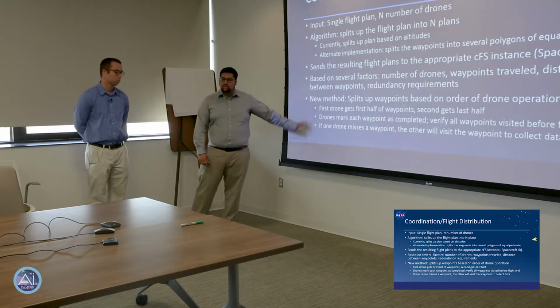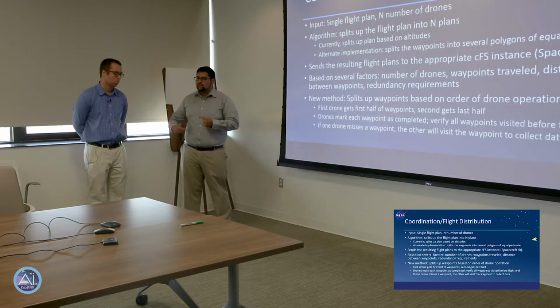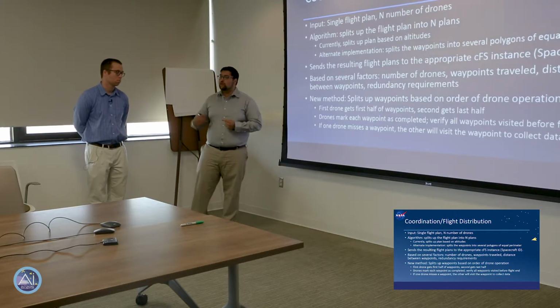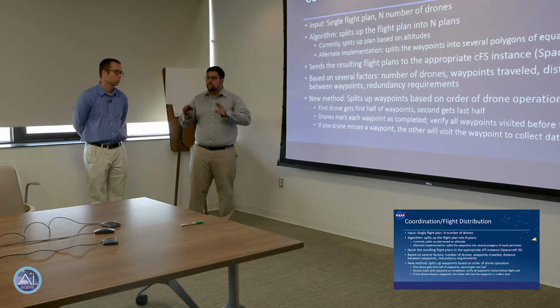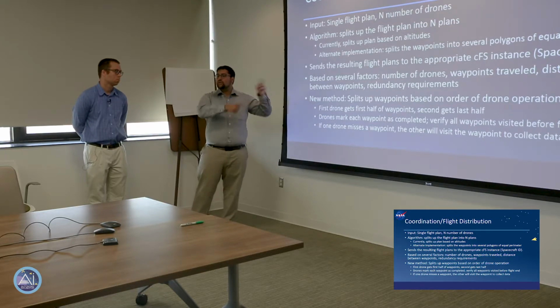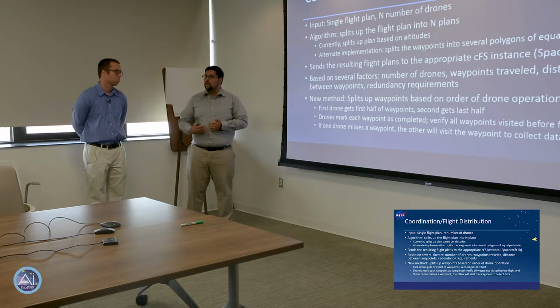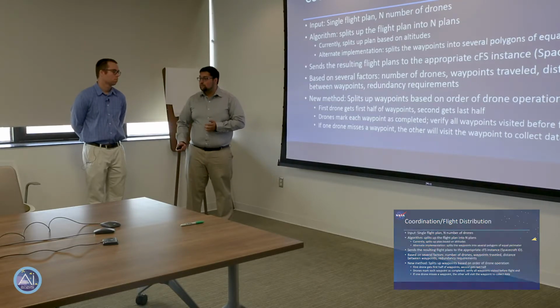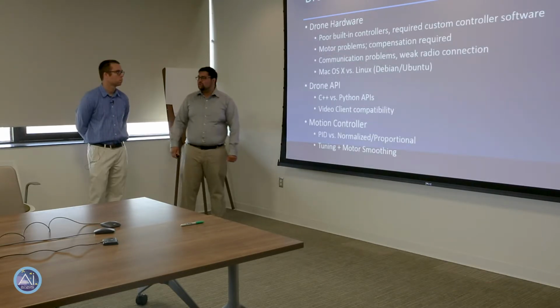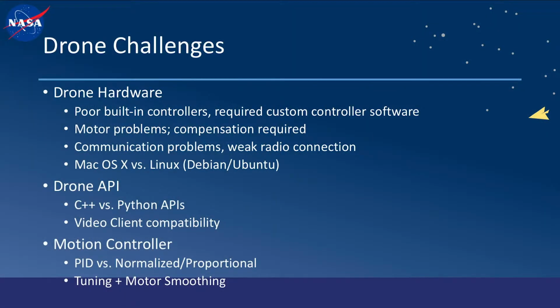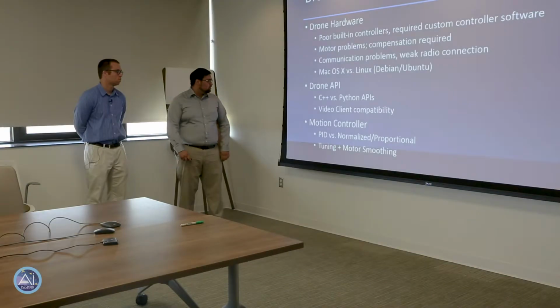The nice thing is that the system is always polling and seeing how many drones or free flyers are in the system. So if there's two and a third one joins in, it recalculates the flight points based on how many more waypoints need to be visited and what has already been done. There were some challenges working with the drones, mostly things around communication, issues with Wi-Fi, issues with interfacing with our computers, but we worked through them all pretty fast.